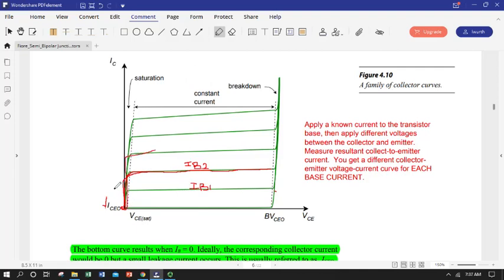And we also have a few benchmark names. We got some vocabulary going here. Okay, so this dashed line that represents these little knees where your collector current heels over and follows the flat line, that's called V collector emitter saturation, VCE sat, and you will literally see this term on a spec sheet. So that says that's how much voltage I have to apply collector to emitter to start entering this flat region where I might want to operate if I'm operating my transistor like a switch.